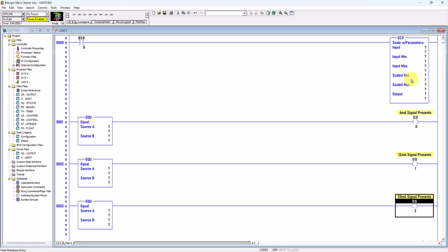Okay, so I will refer to the manual, the PLC analog input manual for the valid analog input data range. So you can go to internet, Google the model number of the analog input module, and then download the manual and then refer to the input data range.